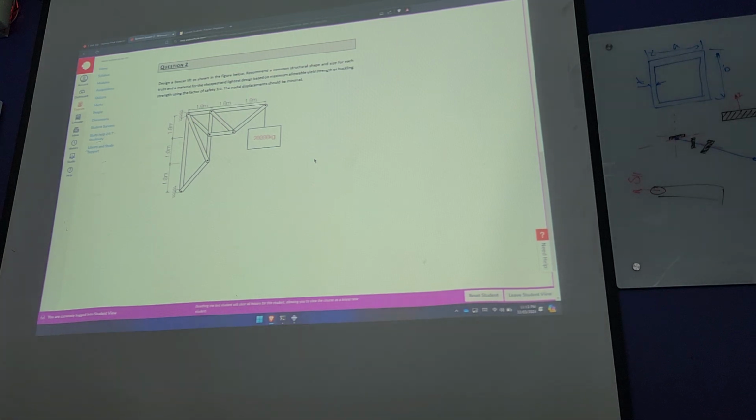So the options are newtons, millimeters, megapascals, or newtons, meters, pascals. Very easily you can mix them up, and all of a sudden you are out by a factor of 100 or a million. Yeah. So keep track of those units.